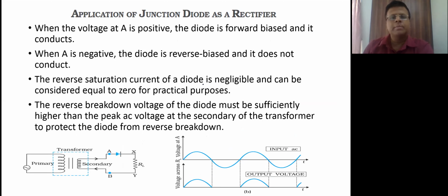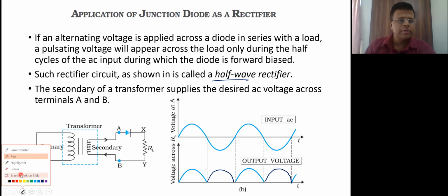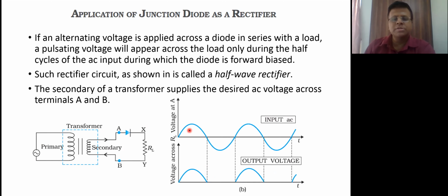Okay. I think, but before that, what is written here? Can you explain again the half wave rectifier? Okay. So in the half wave rectifier, as I told you, during the positive half cycle, that is this region, this diode is forward biased. So when it is forward biased, we know that the current flows. Forward bias condition means your diode acts like what? Short circuit.